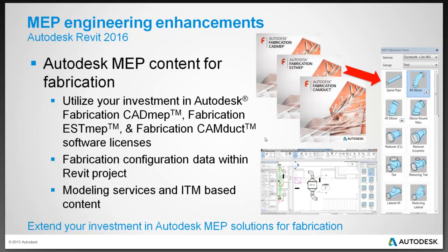Fabrication components provide detailed connection definitions, more granular control on fitting definitions, standardized segment lengths, again leading to more accurate lengths, quantities, and coordination. Modeling with these components in Revit provides detailers in construction firms greater certainty that the model accurately reflects the intended installation.